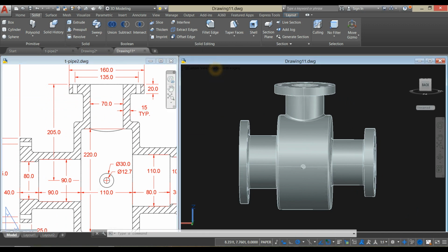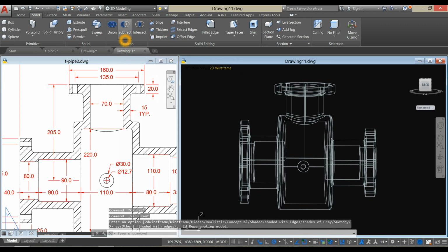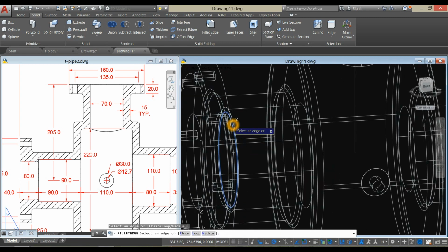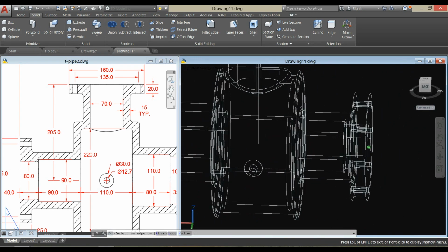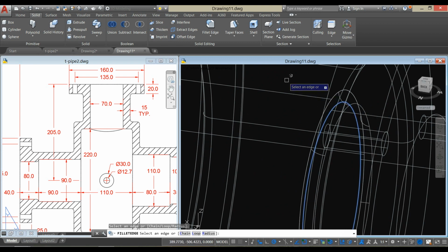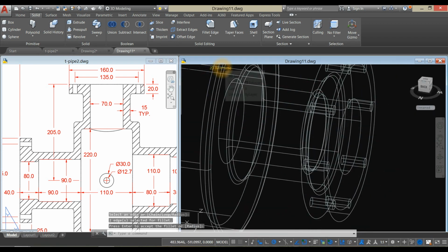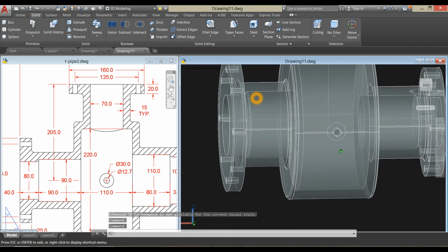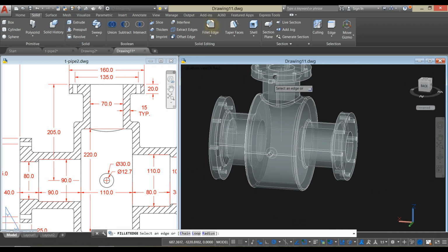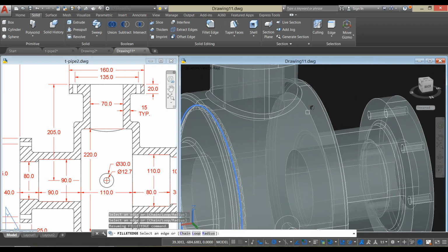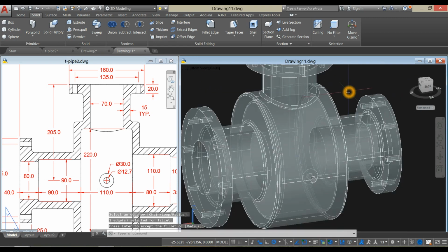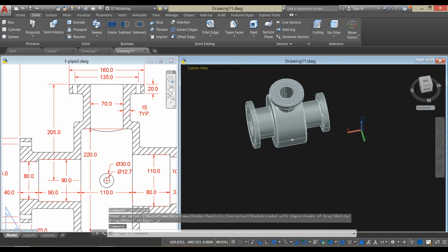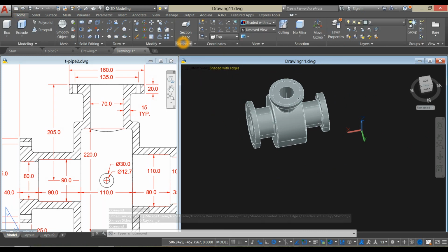inside. So change this to the wireframe. Fillet and apply it here. This side, see this one here, inside. I'm gonna show you what happened doing x-ray. See this one here and this side here and another one inside and this one inside. I'm gonna change this to shaded with edges. I'm just gonna check if everything is okay.